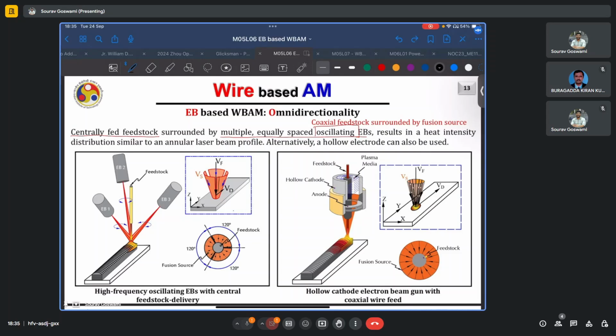Typically your beam will be very fine, but because of the high speed with which it can be deflected and because of the very lightweighted nature of the electron particles, we can deflect it at great speeds so that it forms this curtain of energy, so that it almost appears not like a thin beam but like this hollow cone of beam.